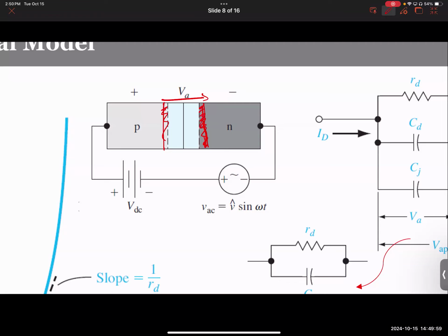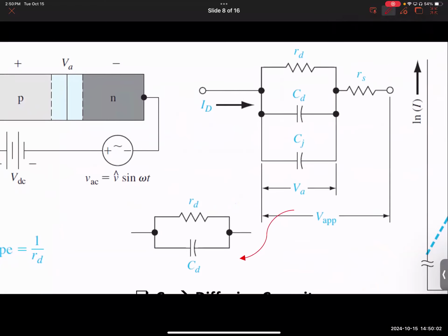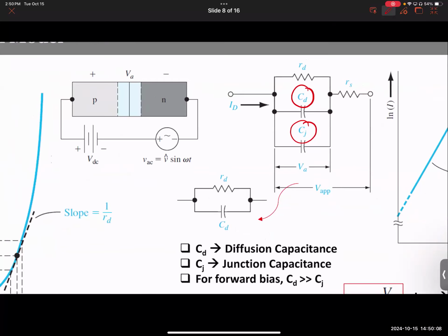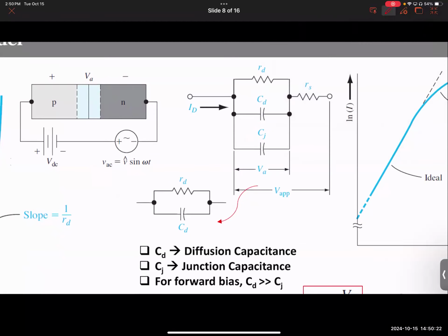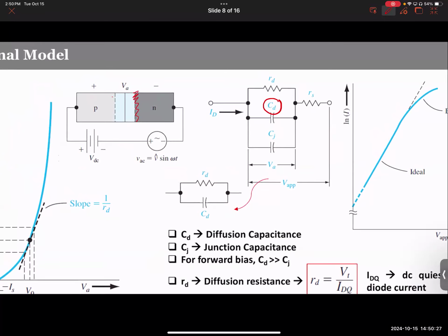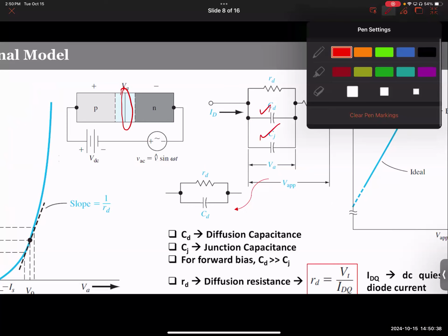So this could be represented with another capacitance. Junction capacitance is one. The other one is diffusion capacitance. Basically, we name it diffusion because the additional layers appear because of additional diffusion. So more charges diffuse away when you apply negative, or say reverse, bias. That's why we say it's a diffusion capacitance. Diffusion capacitance represents the extra charges that appear when you apply extra bias. Junction capacitance represents what you already have just because of having a junction. There you go. You have these two components already covered.